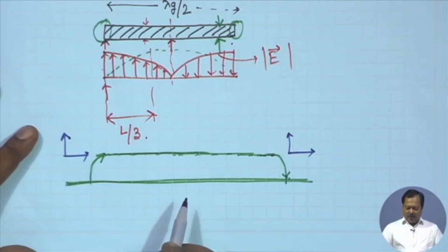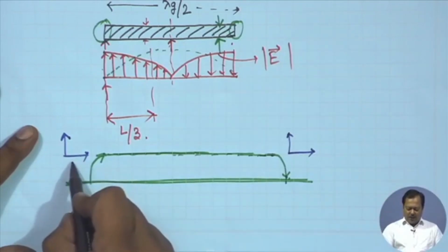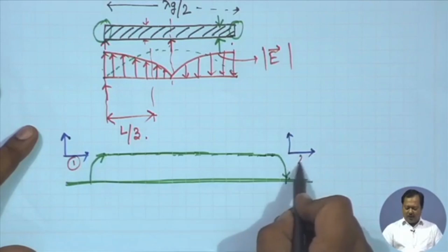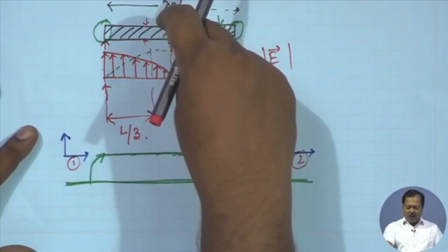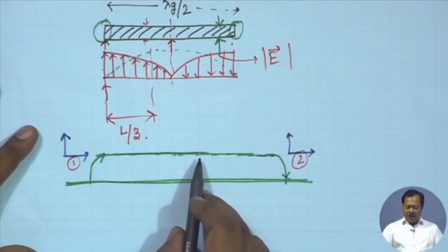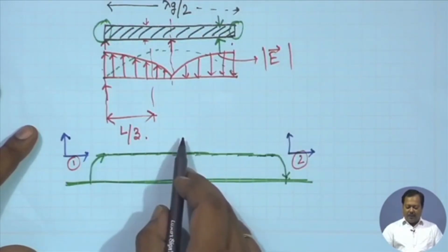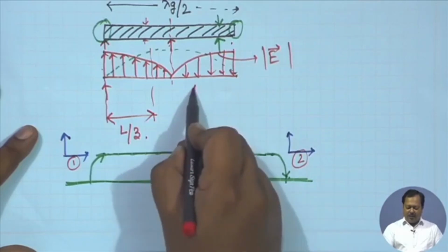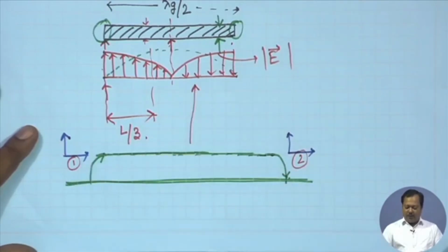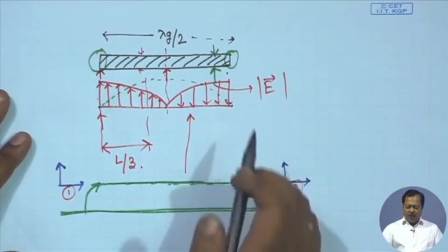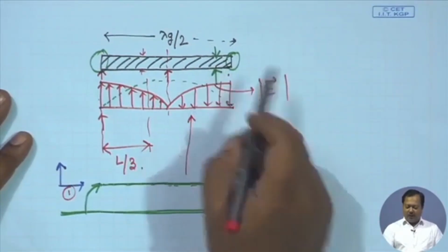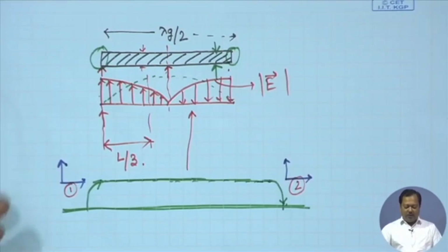In that case, we see that these two electric field components, let us say this is 1, this is 2, are in the same direction looking from broadside, and we will have maximum radiation intensity in the broadside direction from these two fields. So, to increase the radiation, we have to increase the width of this resonator, and that is how we obtain a rectangular patch resonator.